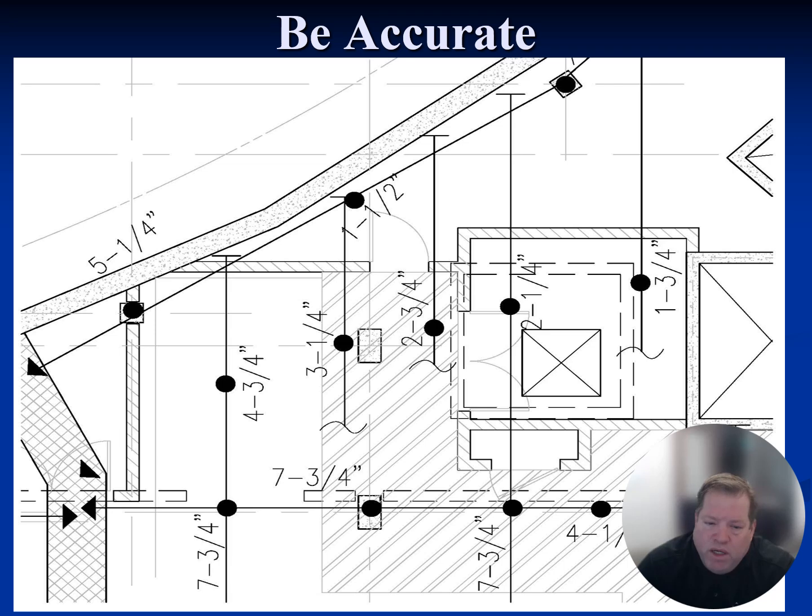The big difference between post-tensioning and rebar is PT is active reinforcement. It is there 365, 24/7. It never goes away, provided the strand is still there. That's why we do a stress check and an ultimate strength. In a lot of ways, the stress check is probably more important because the everyday condition occurs, as stated, every day. The ultimate strength, where you increase dead load by 20% and live load by 60%, may never occur, and hopefully it doesn't. Obviously, that's life safety, that's important, but the stress checks of what we do every day with active reinforcement are extremely important.